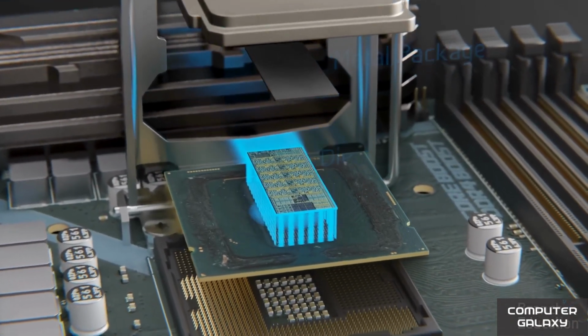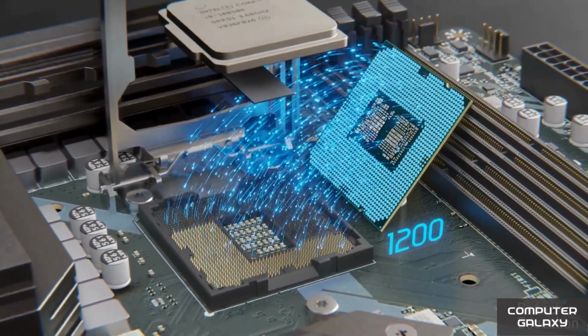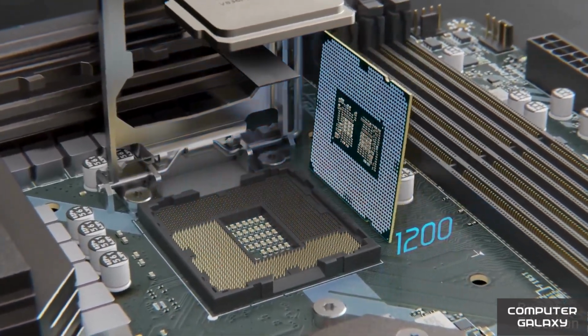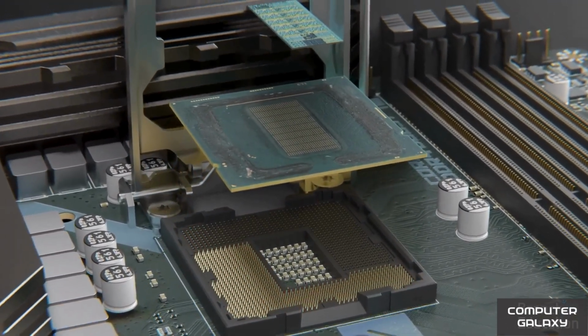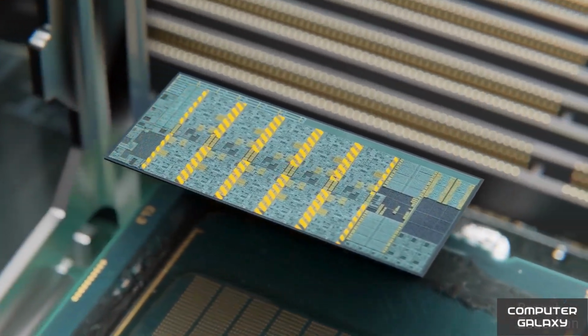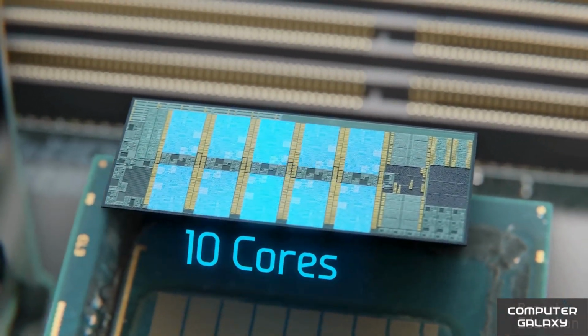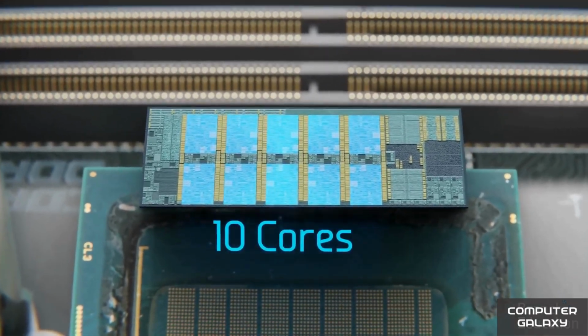This die is mounted on a printed circuit board that distributes the 1200 connection points to landing pads that interface with the land grid array on the motherboard. The integrated circuit inside has a few different sections, but perhaps the most recognizable are the 10 cores where programs and instructions are run. Each core is quite complicated.